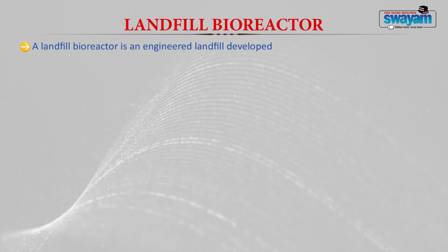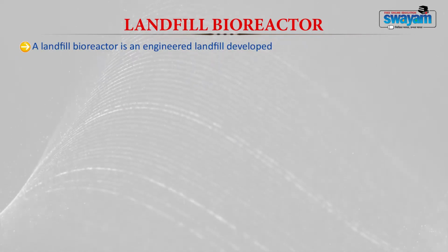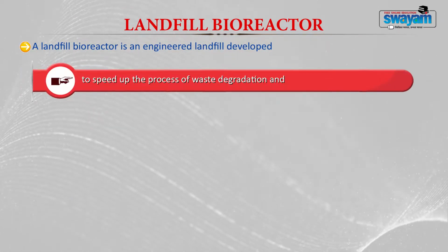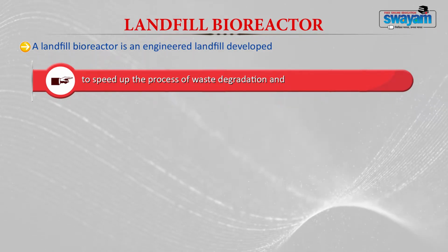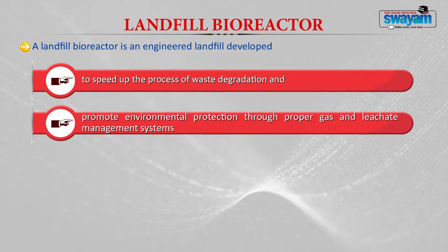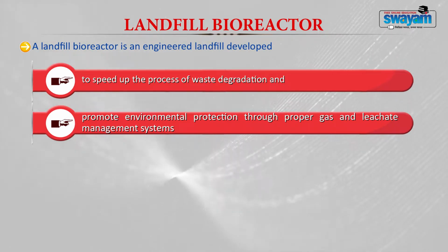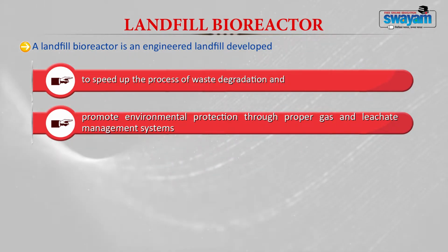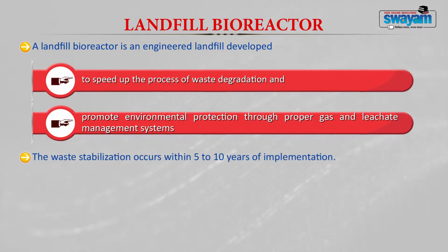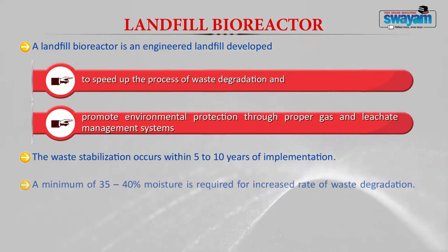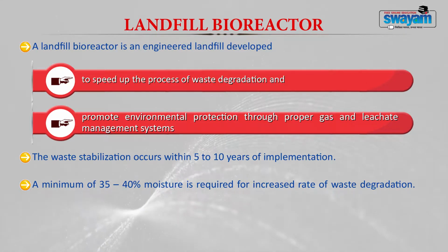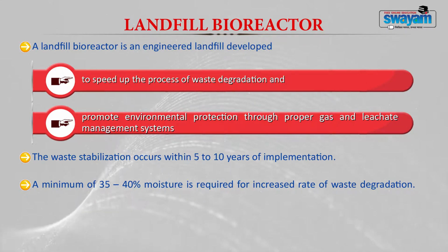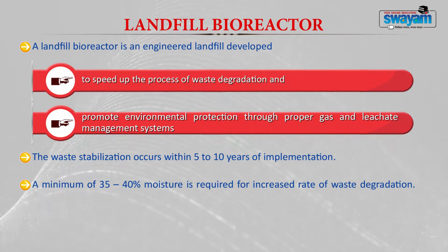Landfill bioreactors are again engineered structures developed to speed up the process of waste degradation and to promote environmental protection through proper gas and leachate management systems. Within a landfill bioreactor, the waste gets stabilized much faster, within 5 to 10 years of loading. A minimum of 35 to 40% moisture is required for the waste to degrade at a faster rate.